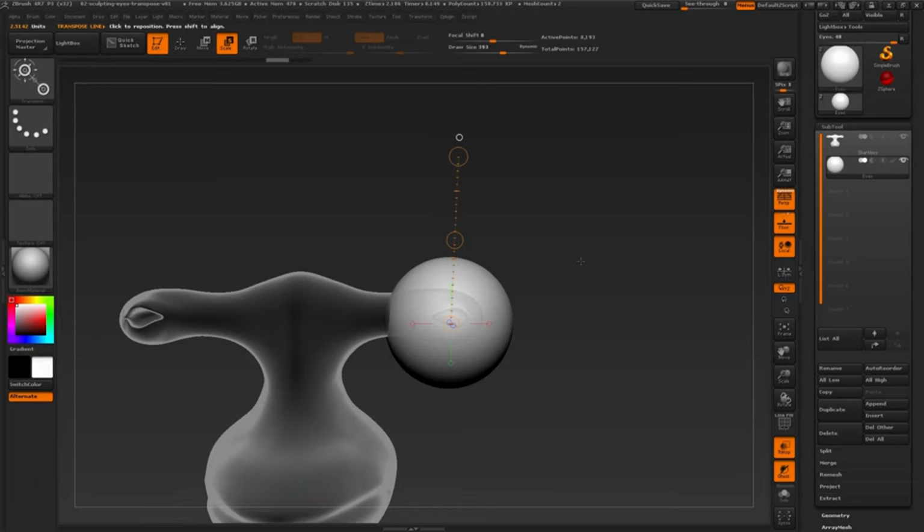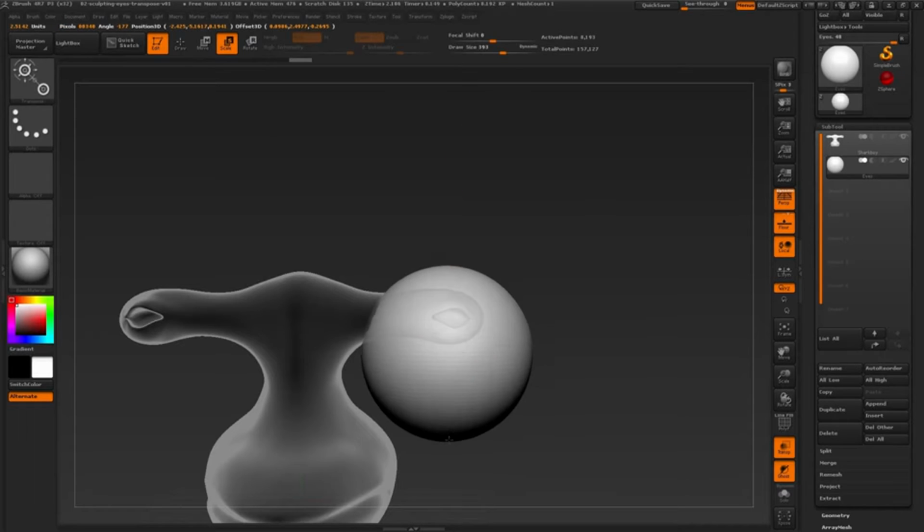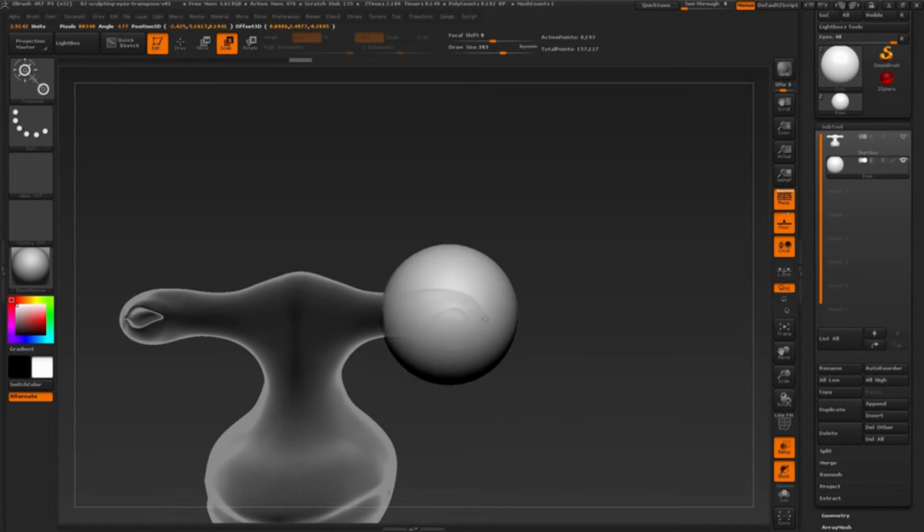to undo. And instead, let's click inside of the top or bottom options, which will scale the mesh without changing the shape or deforming the mesh. Now if we click inside of the top circle, by dragging away from the center of the action line, this will scale the eyeball larger. If we drag towards the center, this will scale the eyeball smaller.